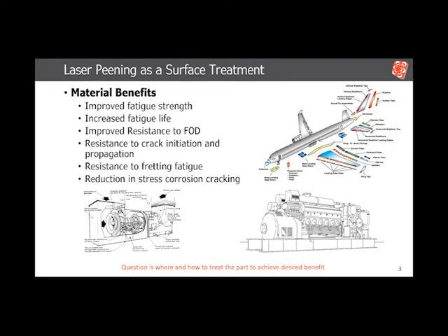Fretting fatigue is another area as part of that. And what I really want to demonstrate and show today is that the part that's really becoming important for the implementation of laser peening or any engineered residual stress is really our ability to model and demonstrate the benefit of a residual stress and then compare some of those profiles and opportunities for improving fatigue resistance that we didn't have years ago.